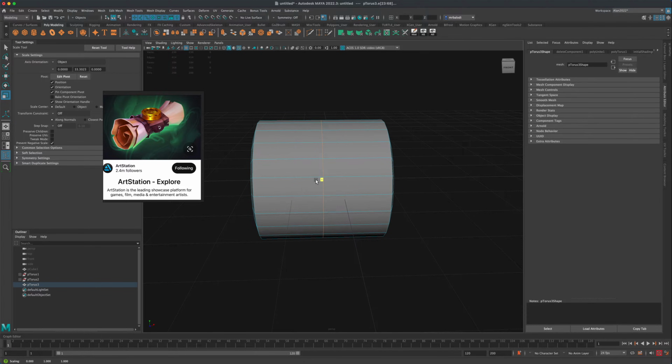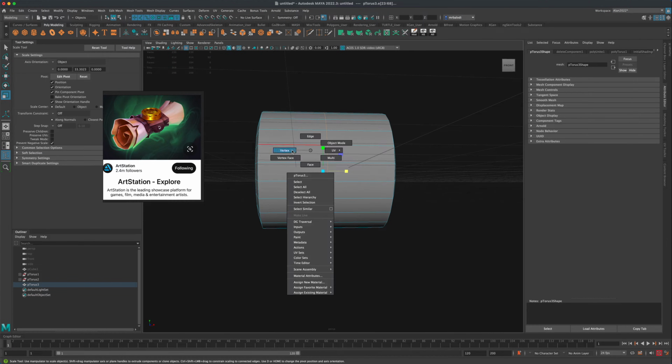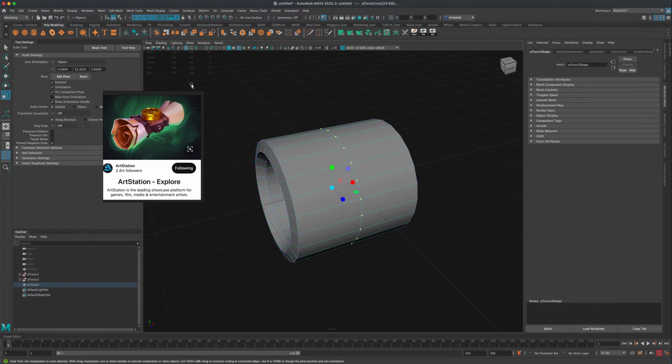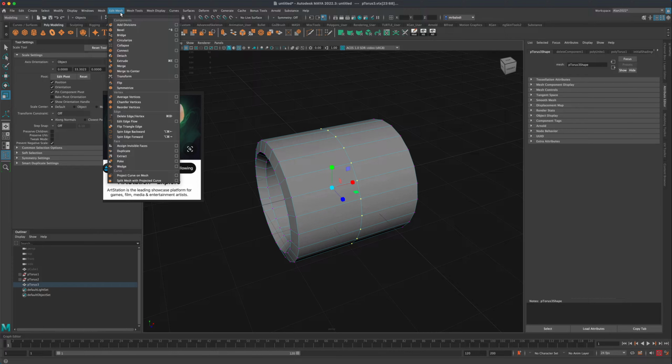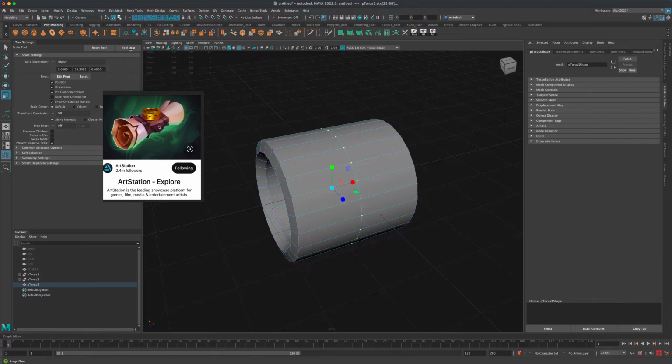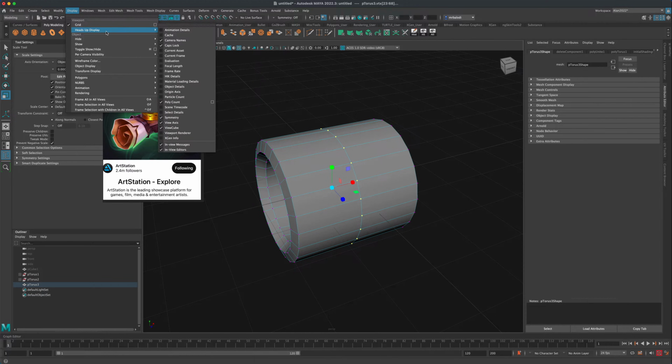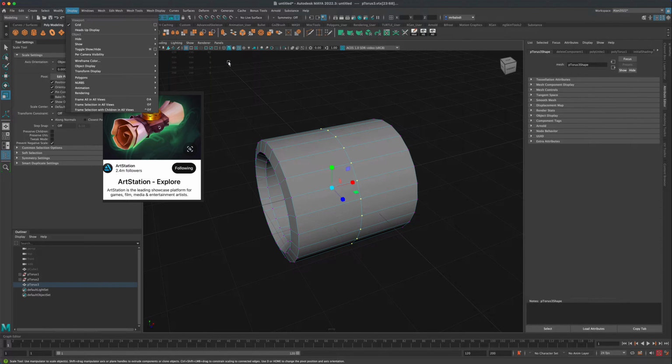And once they're connected, we can go to verts. Let's select these verts, go to Edit Mesh, and do a merge. And when you do a merge, keep in mind you can look at your verts on your heads up display. If you don't have that, it's under Display, Heads Up Display, Poly Count. That's what these numbers are, right?